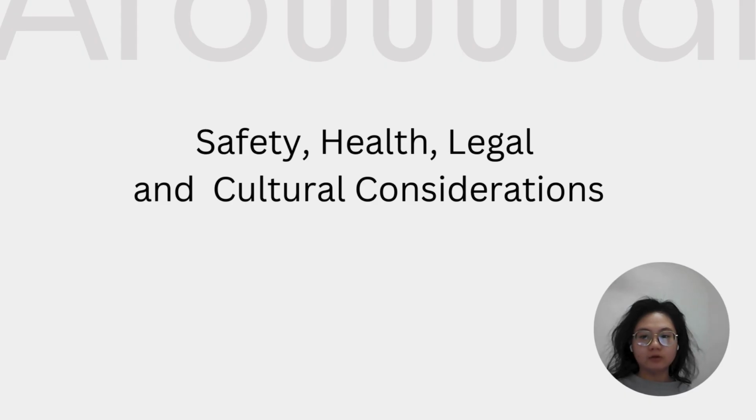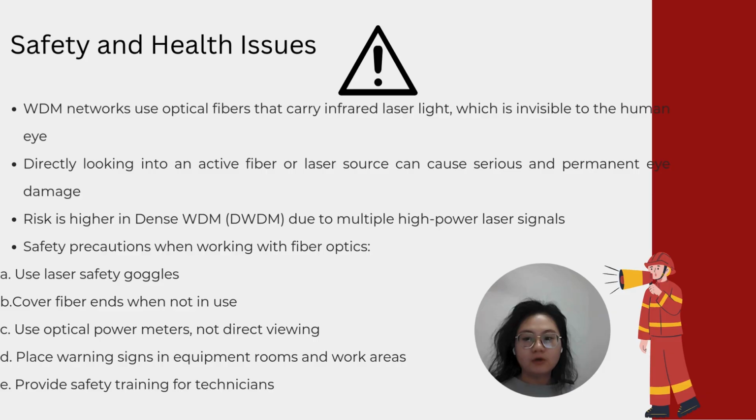Now I would like to talk about the safety, health, legal, and also the cultural considerations. For safety and health issues, WDM networks use optical fiber that carries infrared laser light which cannot be seen by the human eye. Looking directly into an active fiber or laser source can cause serious and permanent eye damage. The risk is higher in dense WDM systems because multiple high-power laser signals are transmitted at the same time.